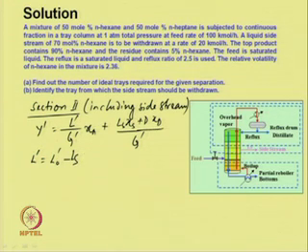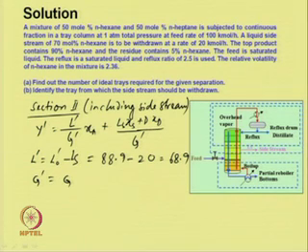So, the flow rate in this section would be reduced by Ls. So, it would be equal to 88.9 minus 20, which is equal to 68.9. Now, the gas flow rate G dash would be similar to the rectifying section, which is equal to 124.46.